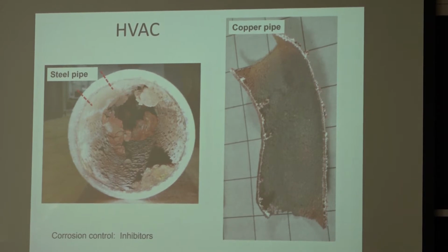So if your flow rate is high for copper, there's a threshold, and it's not much higher than what we use. So one reason for having, let's say, a 1/2 inch or a 3/4 inch line is you don't want the water to flow through fast, so it causes the erosion and the damage to the protective film. So what happened in that elbow, it was just too fast with the circulation, the vortex effect in the corner, that it lost thickness. And you can see on the inside wall, it's got plenty of thickness, so it really affected preferentially the outside. And that's all just physical weathering, right?